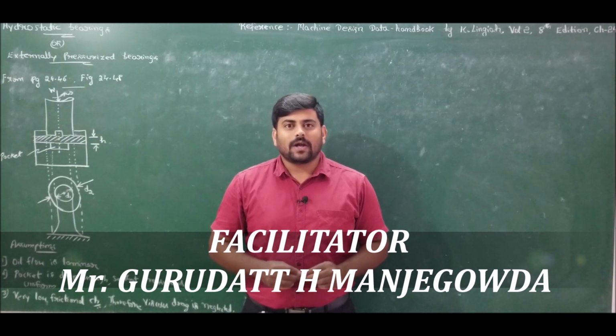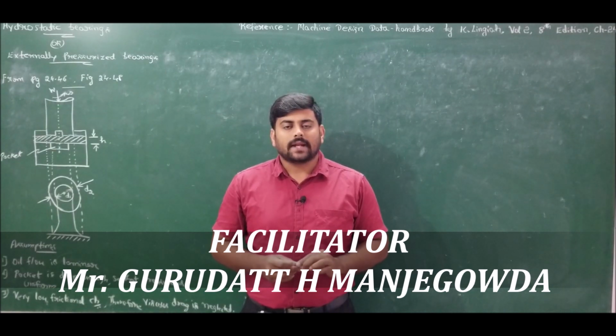Let us continue from the point where we stopped in our previous lecture. In our previous lecture, we derived the expression for oil flow rate, that is discharge, and also for pressure distribution in a hydrostatic step bearing. Continuing from that point, in today's lecture, let me derive an expression for load carrying capacity and power loss due to friction in a hydrostatic step bearing.